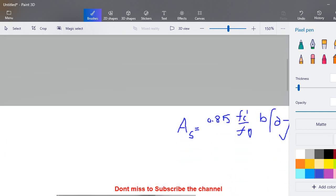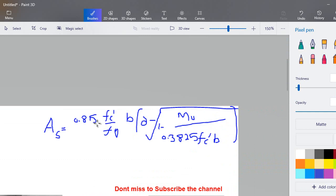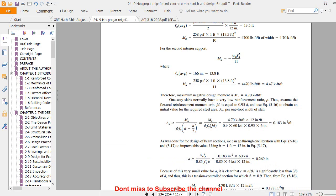This is the formula used in the direct procedure by ACI, and all the materials are available here. We have b, that is 12 inch, depth 6 inch, Mu is calculated, fc prime is 4000 psi, and fy is 60,000 psi.